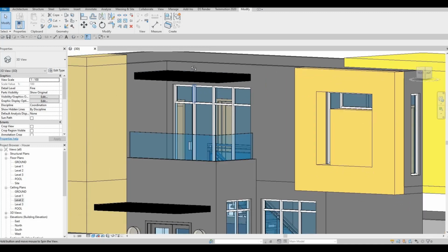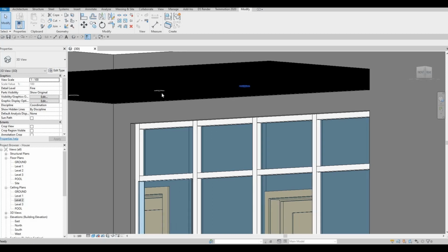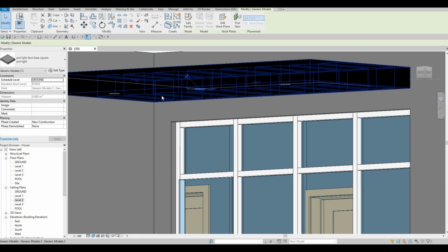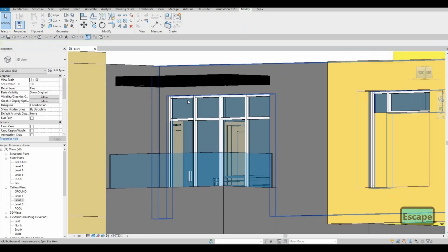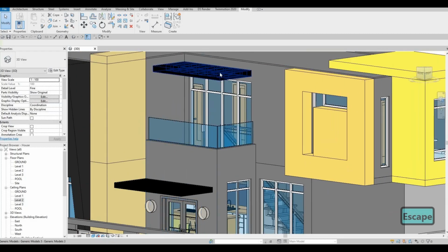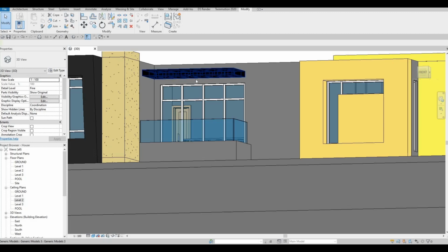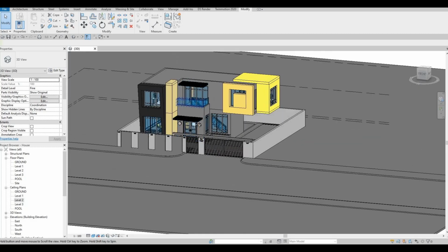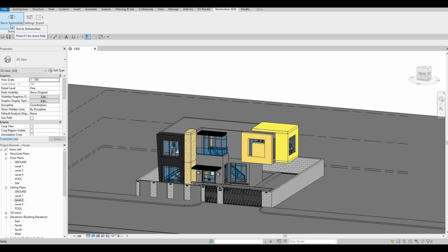Also, what I want to let you guys know is I just added the same in place model right here, which is the square base pot light. I added it on the awning for the first and then the second floor. So just add 3 of them. I spaced it out around 1,000. And then after that, you want to make sure that this is under fine. Save it again, and then go to Twinmotion 2020 and then select Sync in Twinmotion.